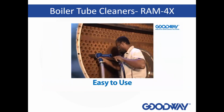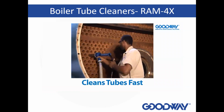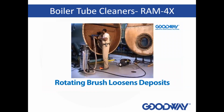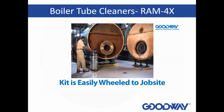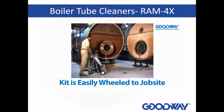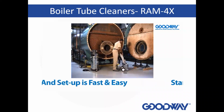Now these brushes come in all different sizes. Generally, boiler tubes are sized by the OD of the tube, and they go from 1 3/8 to 4 inches. The most typical size would probably be 2.5-inch OD. And you can see it's a pretty simple process. You wheel the vacuum up to the boiler. You got your tube cleaner there, which you're going to actually lay down on the handlebars.